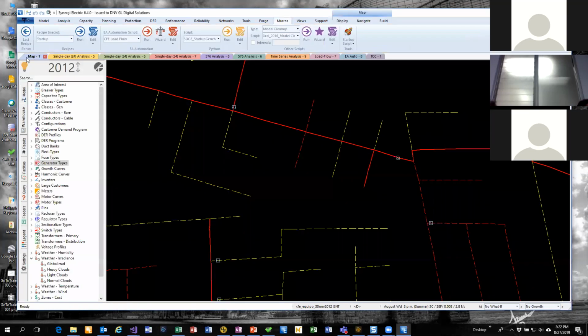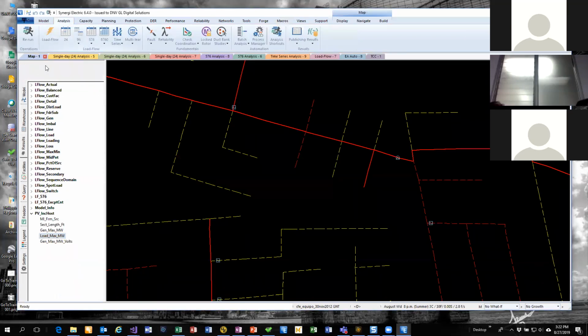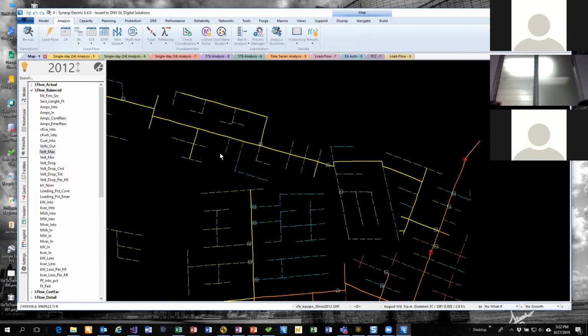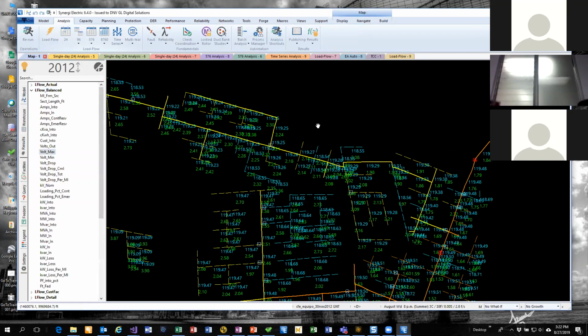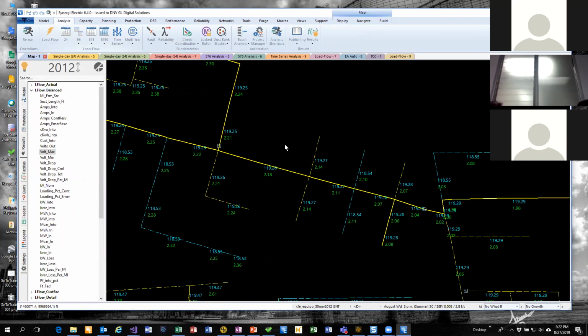The use of Excel is all over the place in Synergi now. If I go in here, I just run a load flow. And if we wanted to look at something like our balanced results here, we can click on this once and color the map. We could right click on this and show annotation. So we can put the maximum voltage on the map as annotation.